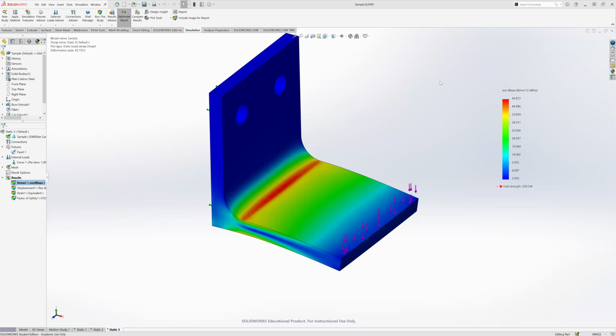Okay, so that's actually a very good question. Pretty much how it calculates it, if you look back at the last video, and I'll try to do this because I don't have my notes up in front of me, is that the formula for factor of safety is the allowable stress over the actual stress. So if the allowable stress is, let's just say, 500 psi and your actual stress is 100 psi, there would be a factor of safety of 5.